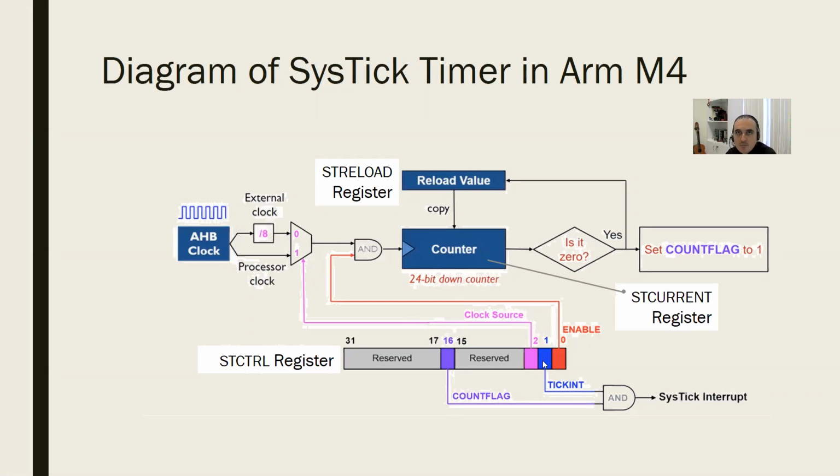The second one, let's get to the first bit 2, the third one, because it's easier. Again, the pink line connected to a multiplexer. What was a multiplexer? Depending on the control signal, which was connected laterally, not from behind, laterally. Depending on that signal being 0 or 1, one of the inputs is chosen. So this input is chosen.